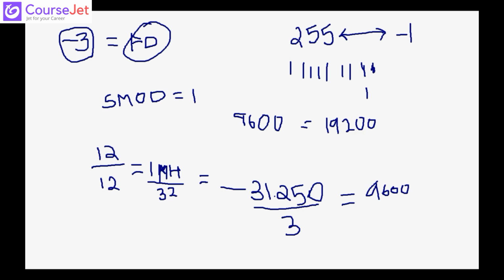While 0 is equal to 0, stay here only. The semicolon indicates stay here only, as your while loop is true. As soon as it becomes 1, while 1 is equal to 0, the condition fails and it will come out. Then clear your flag, TI equal to 0. This is clear?